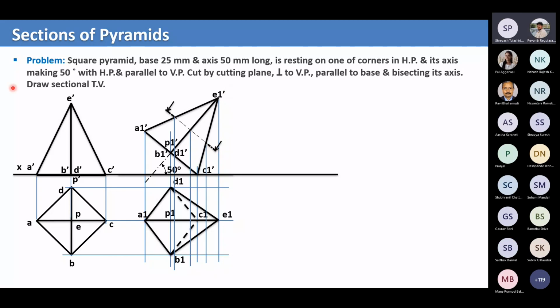So now the first thing when you rotate the pyramid is you should get the positions of the base in top view, right? So for that you need to just tilt it and then draw the vertical projections here and draw the horizontal projections from here, and wherever they are meeting, those points will be the respective points. So respective points, what does that mean?